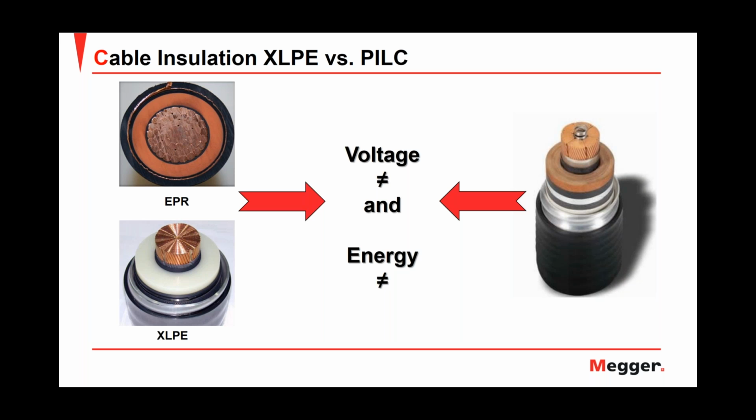I also need more energy to sustain the arc in that fault in comparison with the other insulations, the EPR or the XLPE. So the type of insulation makes a difference in terms of fault location.